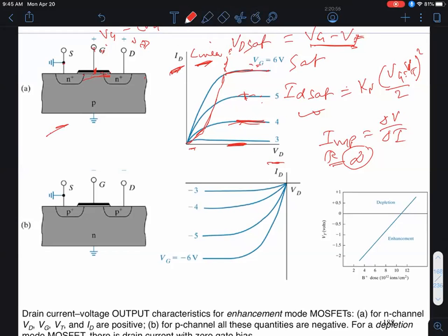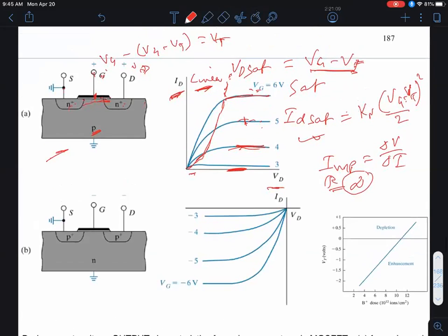Over here, we are looking at the N-channel MOSFET that I've been talking about so far, where you have N plus source and drain and a P-type channel. So now to connect the source to the drain, you have to apply a gate voltage higher than the threshold voltage, okay? So that you form an inversion region of electrons connecting the source to the drain. And if you do that, if you apply now a drain voltage, it's like an ohmic resistor initially.